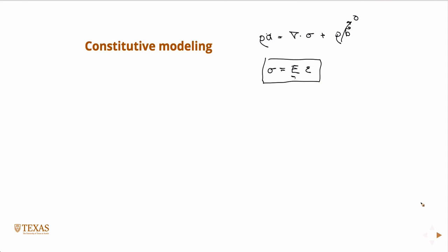But in this course so far, and I know you've seen it in mechanics, but we'll go over it again just for review, we've only talked about stress. We haven't mentioned strain, really. I mean, we certainly haven't talked about it in any kind of detail. So what is strain? Change in length over length, right? Exactly. So strain is the final length minus the original length, divided by the original length, or delta L over L0, okay?